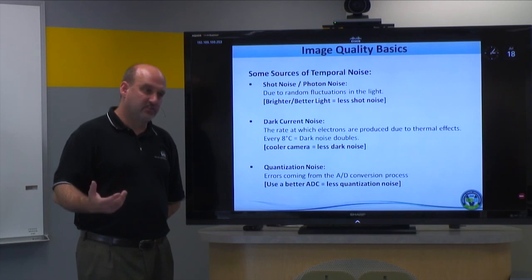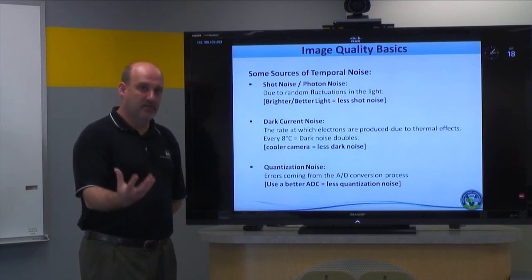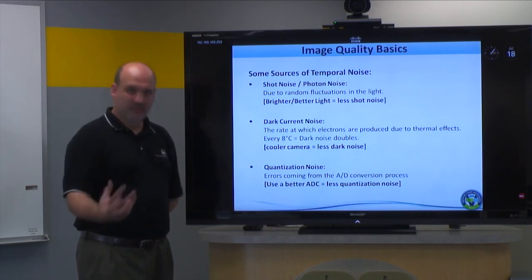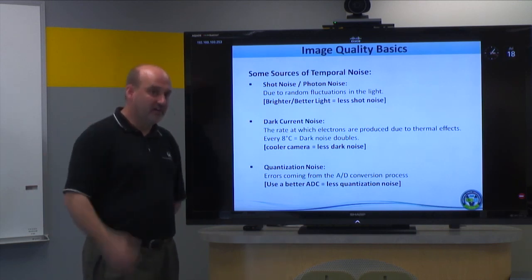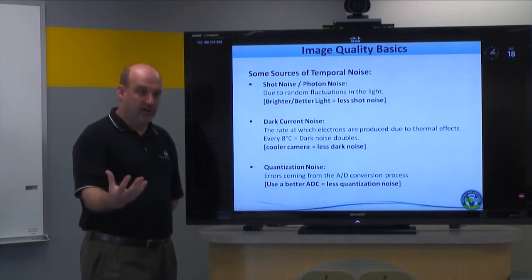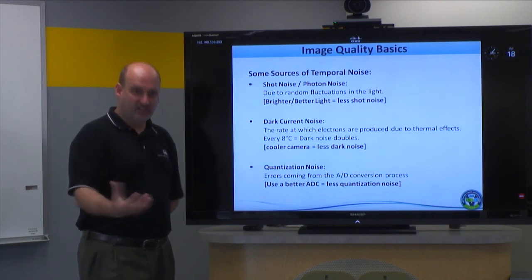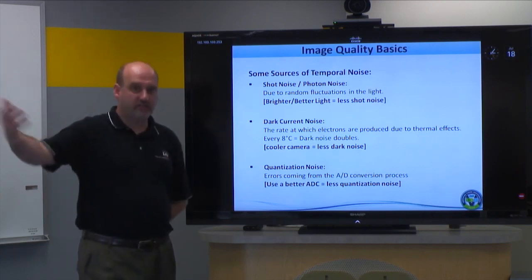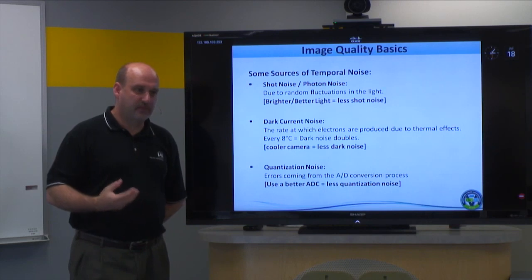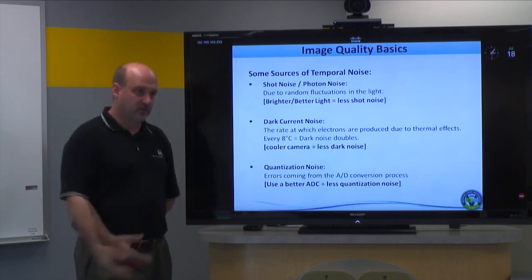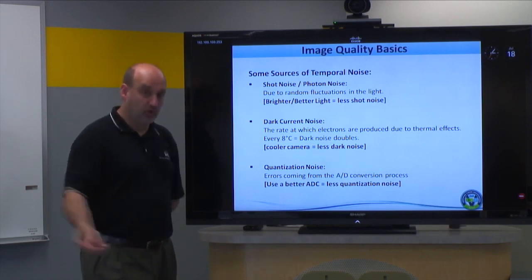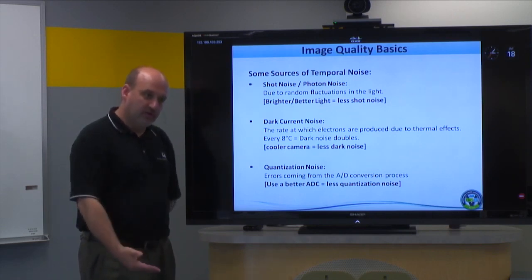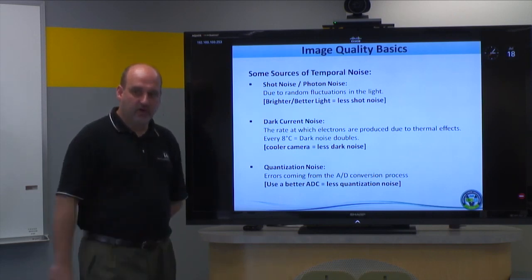And it's essentially the fact that my bucket is not really a bucket. It's a little bit leaky. You can imagine maybe a well built with bricks or something where there's a little bit of light in the side. So if I hold the light for a long time, say I do a 4-second integration to get a real low light image in a scientific type application, you can actually measure those photons creeping into the well, or those electrons that were never really photons, but they creep in the well anyway and get measured, and that's called dark current noise.